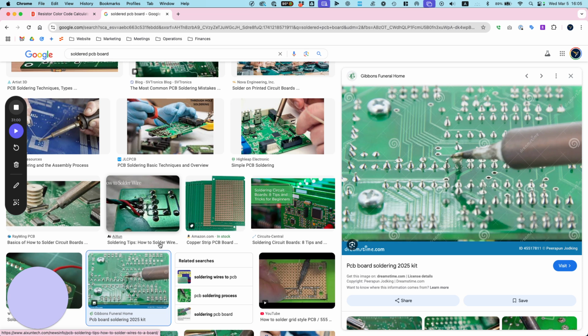But look back up here. When you take out one battery, you take out one parallel set. So what's happened? It goes to twice the current, less power, but you have the same voltage. So the system still stays on, but your capacity is cut in half. Which doesn't really matter when the drone's just sitting on the ground in an idle mode, right? That's how you can hot swap it, because you're still powering with the same voltage. Of course you cut your capacity by half, but you're not draining it at the same rate as when you are flying. So that's why it's okay.